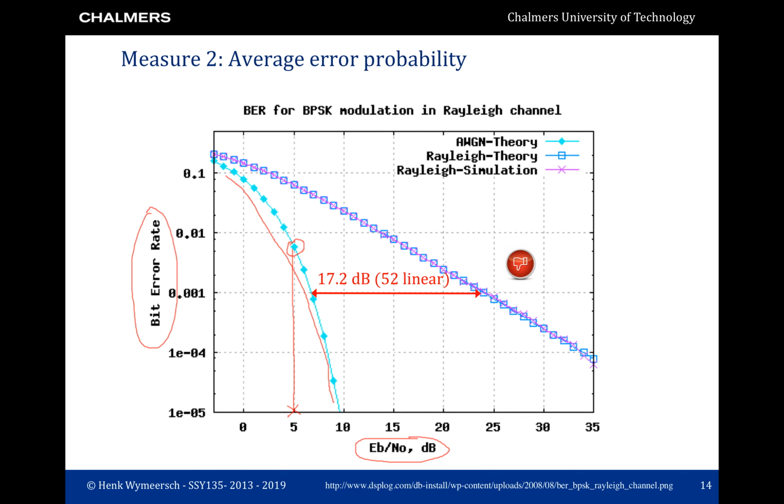The dark blue curve shows the performance under Rayleigh fading. So let's say again the SNR after path loss and shadowing is 5 dB. So we operate again at 5 dB. But now we have in addition Rayleigh fading, so the SNR becomes random with the average of 5 dB. And then our symbol error rate performance will be approximately 0.08, let's say. So a factor of 10 worse.